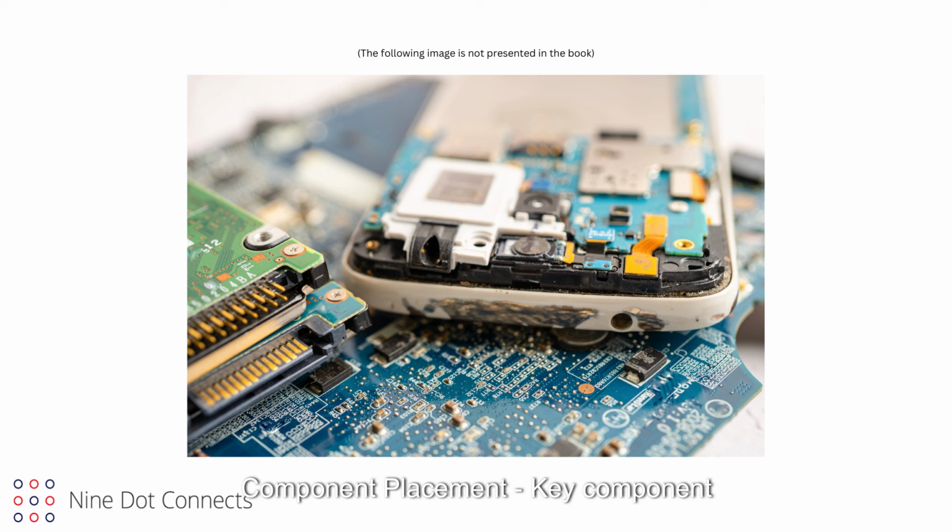Component placement. Key component placements need to be considered. High pin count devices, like FPGAs, microprocessors, and DSPs, need to be placed towards the center of the board, so that the route can escape on all 4 sides. The placement of connectors, and other devices used to communicate on and off board, need their due consideration. With the advent of high-speed communications, placing a connector has consequences for the area of the board surrounding it. Most electromagnetic noise transmitted through the PCB will be through the connectors. Antennas, if required, need their space and shielding.